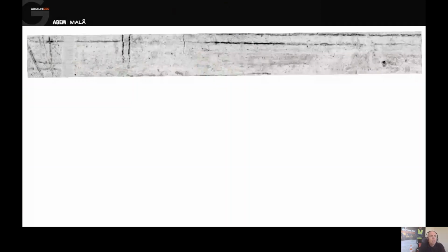This is a plan view. This is just one slice of data at depth. I think this was just over half a meter in depth, around a couple of feet. So this is a time slice, and these are the utilities running along and across the road. There was one utility of interest, and it's this one running down here. It disappears, it reappears. That would indicate either the ground conditions are affecting the signal, or it's changing depth.